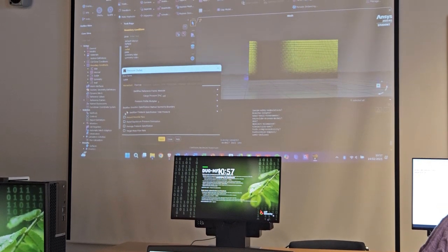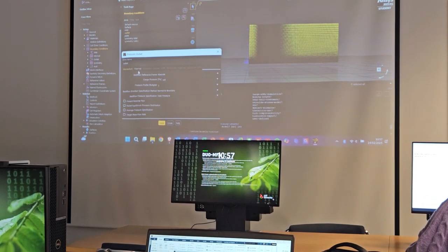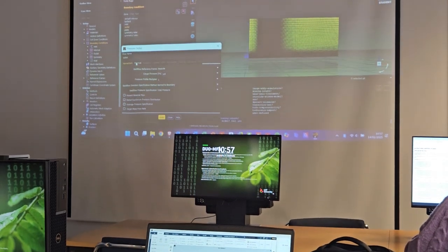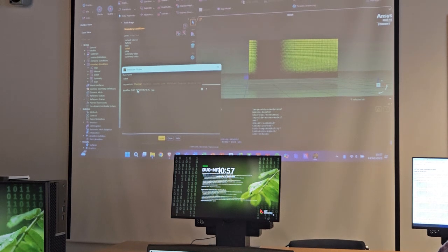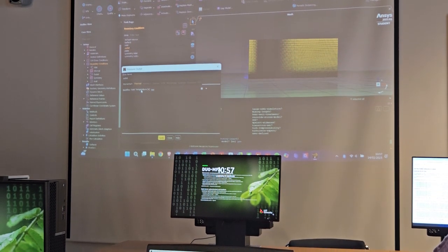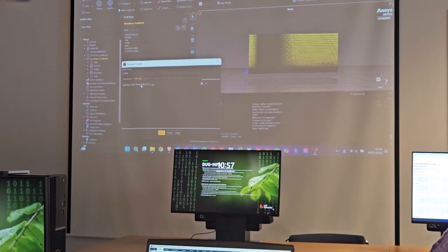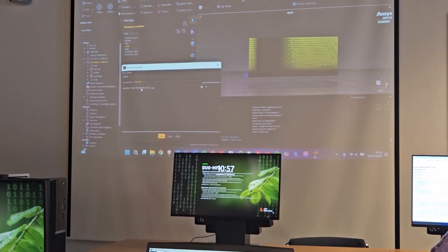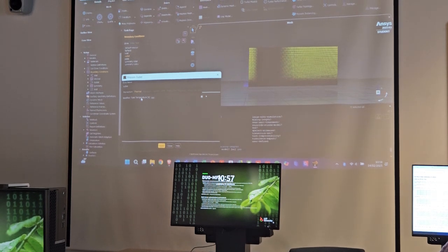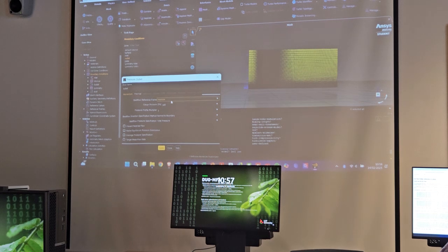Also in this case you can prevent reverse flow, but you don't really need it. Let me apply first so that it saves that option. In thermal you can also set the backflow total temperature. You don't need to set a temperature boundary condition for this case. This is just the temperature value in case of backflow. If there is any backflow, that's the value Fluent will use. But we will not have backflow, so that doesn't really matter.